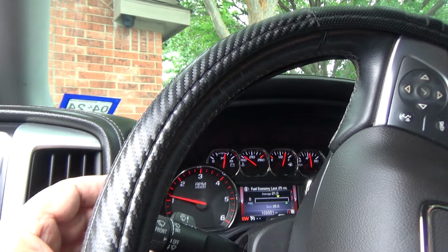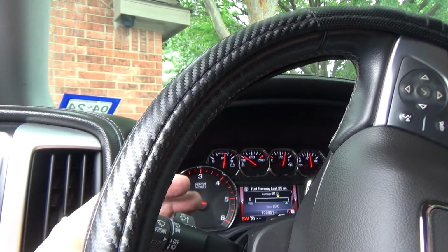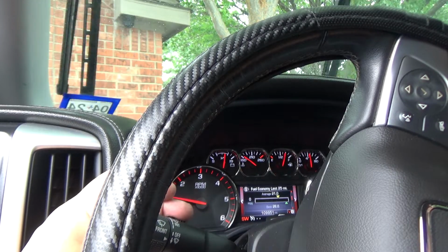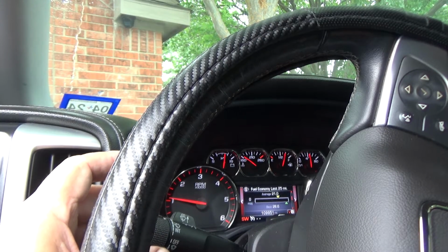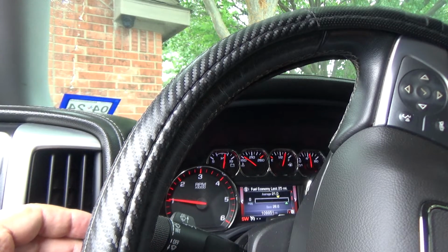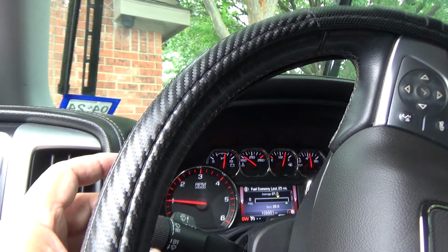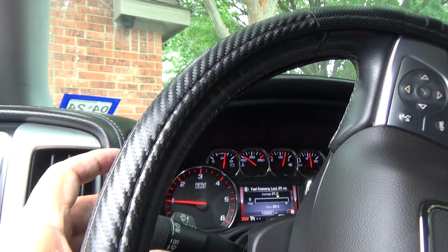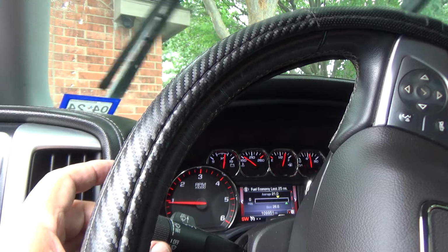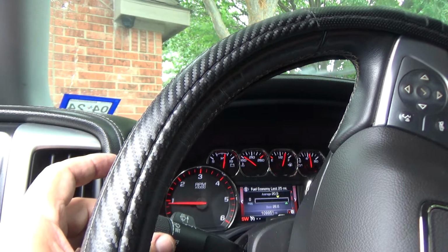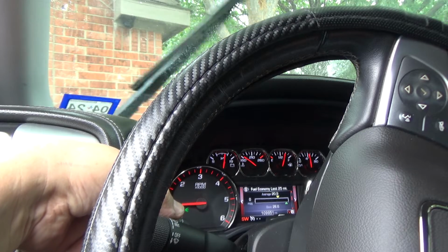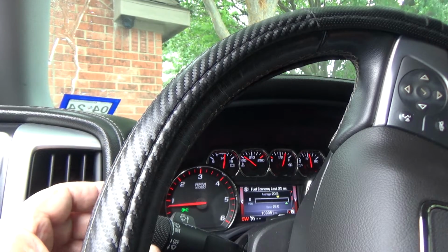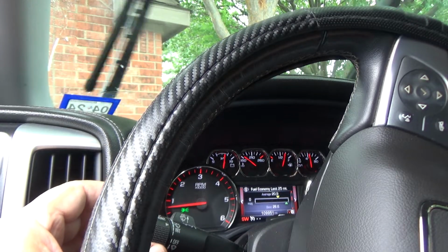So just to show that the wipers only work on low speed, let me throw a little water up here. I'm going to take the switch to low speed, which is what we got there. Then I'm going to go to high speed. No change whatsoever. Go back to low speed. Same speed. Splash a little more water up there. All the intermittent seems to work.